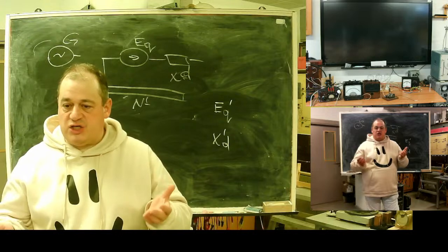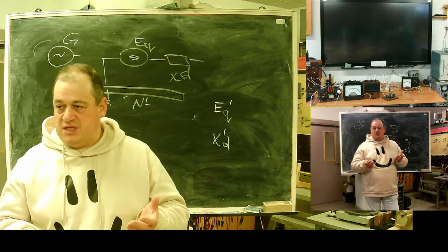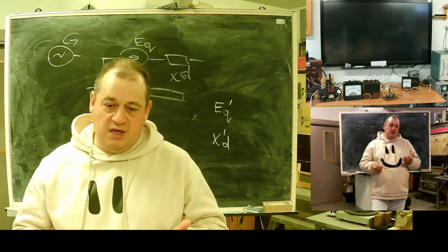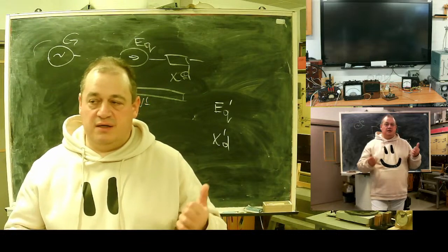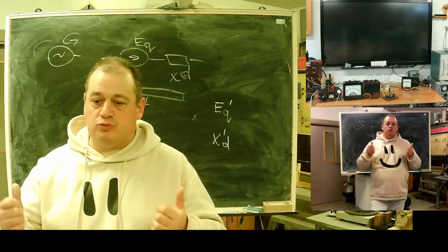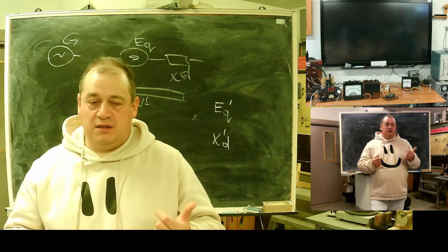Backwards rotation means extremely fast degradation of this bearing. They are not designed, not intended for two-way rotation. It's one thing.